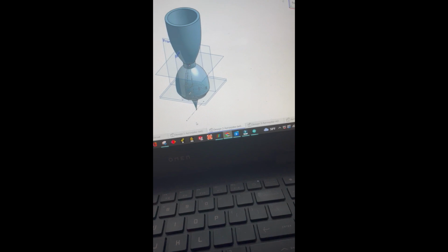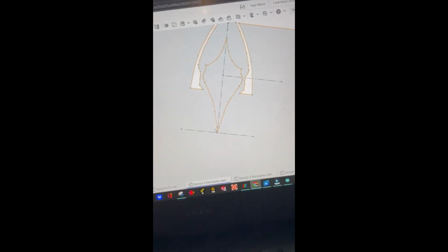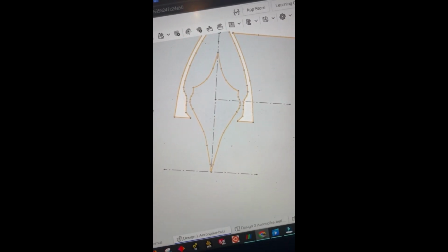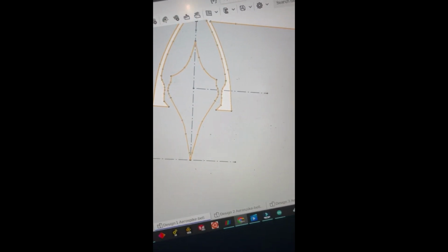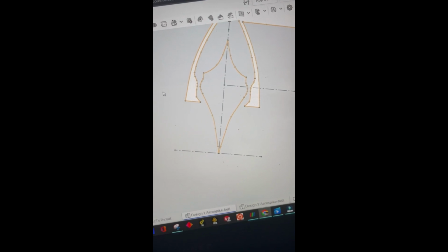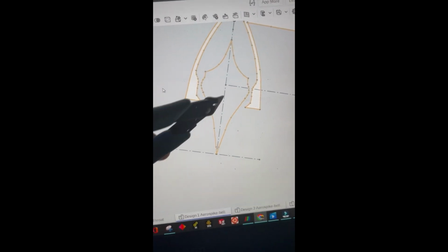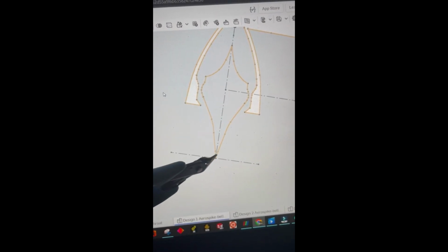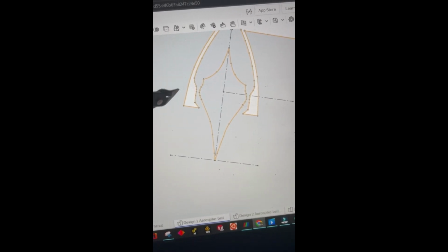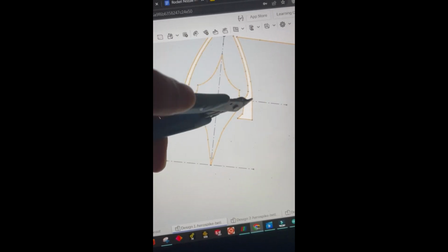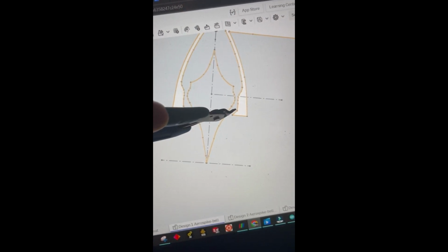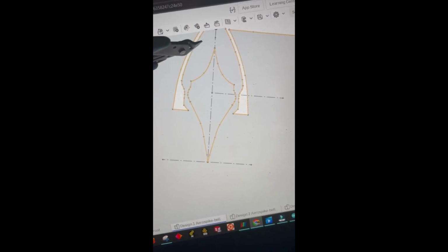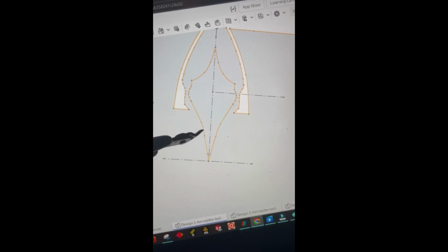So I started by designing our typical aerospike nozzle. You can clearly see that this is a cross-section of your average aerospike. You can clearly see that the actual spike of the nozzle is this thing. Here are just the walls. These are going to be our no-slip conditions, or wall no-slip conditions. All this is going to be where the fluid can go through.